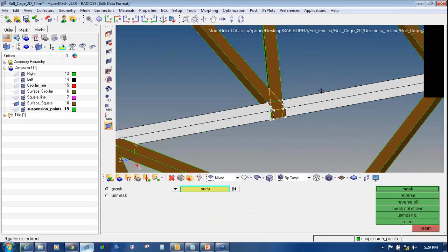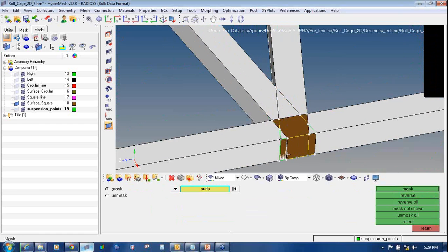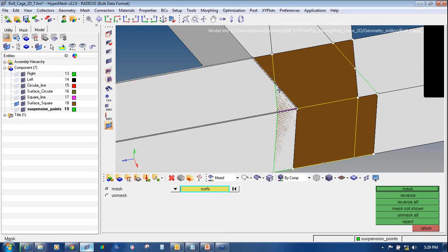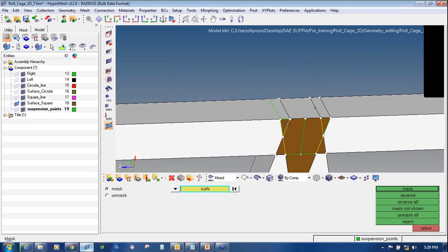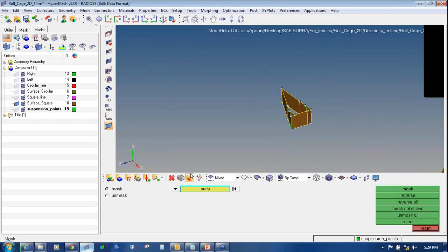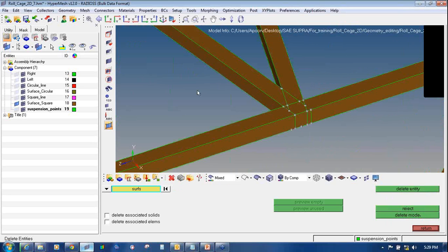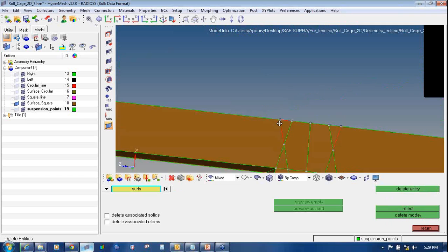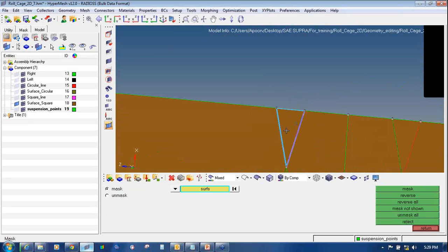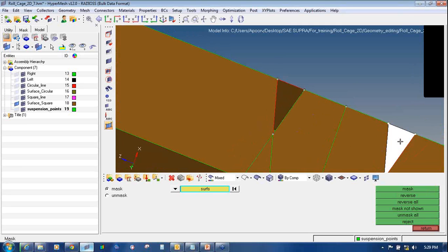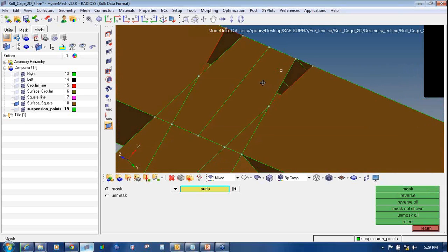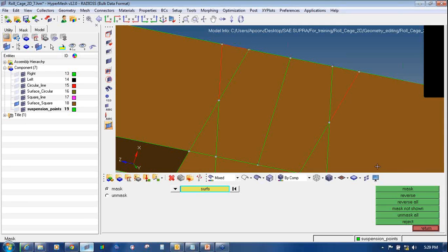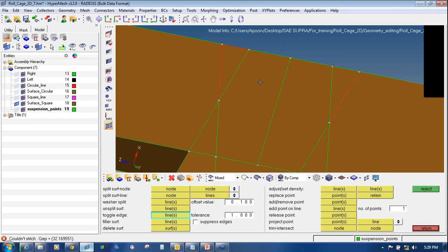then go to mask. It has to be hollow from inside, so that's why we are using the trim. So as you can see, there are duplicate surfaces here and here also. So I will mask them, and let's see if it's completely hollow from inside or not. If it's not, we'll make them edit again. So just delete this, go to mask panel again. So if I go to F5, if I mask this and this one, it's hollow from inside, but there are red edges. So I will go to F11 and toggle them.